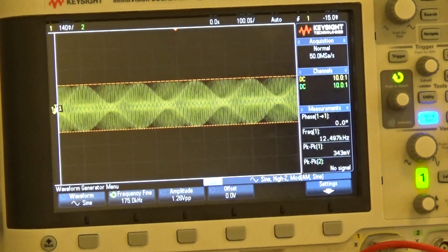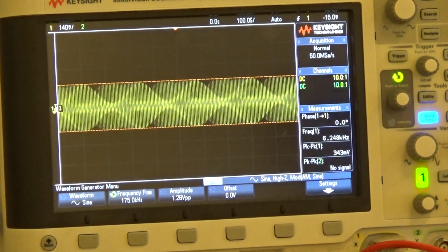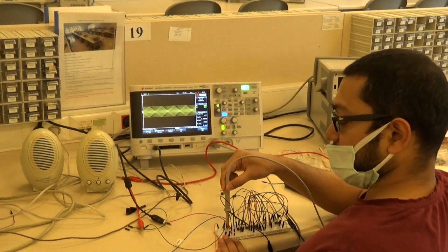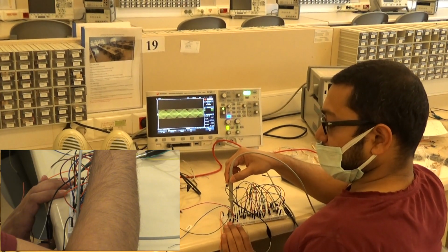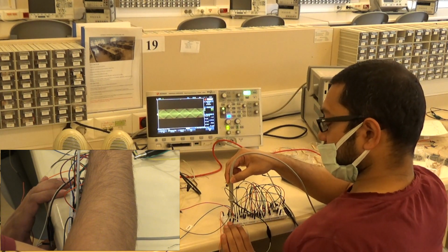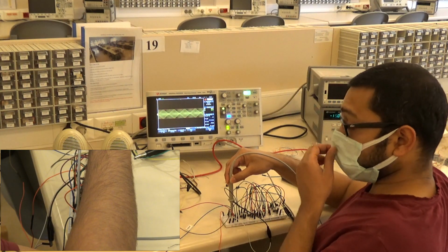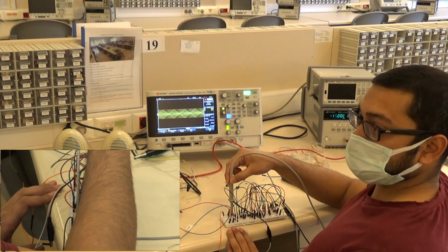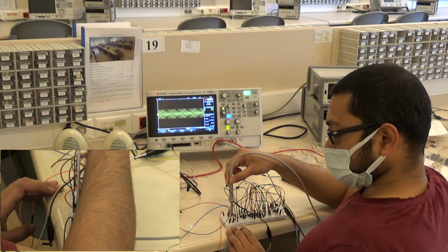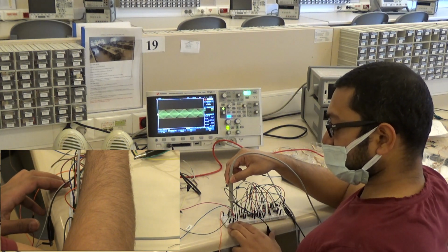After the signal is transmitted, it's filtered at a center frequency of 175 kilohertz. The next part is we will amplify the audio signal, along with the modulated signal. The amplification that we have chosen here is around 65 volts per volt. You need to get more than 65 because the voltage coming from the antenna is in the microvolt range, but just for lab purposes, you can choose a low voltage.